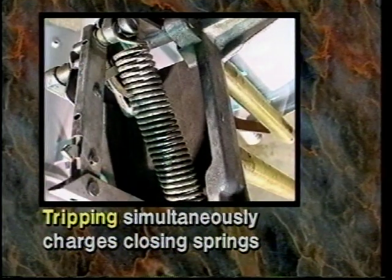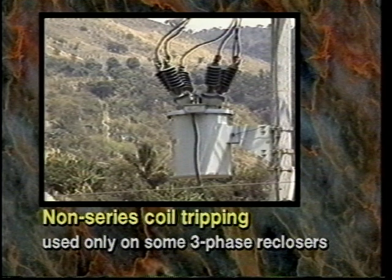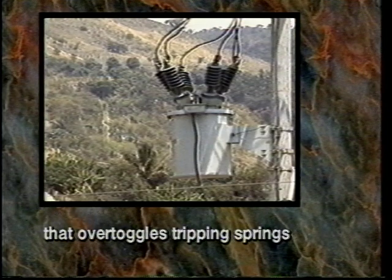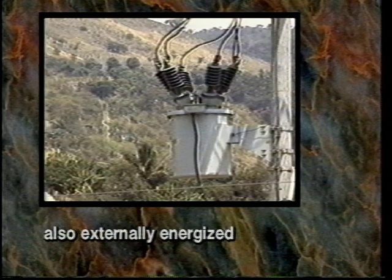Tripping simultaneously charges closing springs that then close or reclose the recloser when the proper closing signal is present, thus making the recloser ready for another tripping operation. Non-series coil tripping is used only on some three-phase reclosers. It may consist of a tripping solenoid energized from an external power supply that over-toggles tripping springs. It may also consist of a tripping spring simply released by a small tripping solenoid, also externally energized.